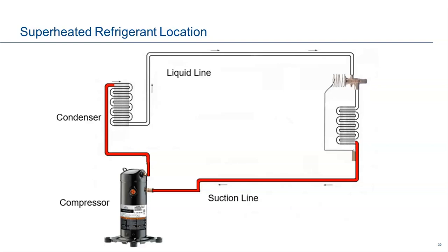If you have a 10-to-1 compression ratio, that is a low temperature refrigeration system. A 5-to-1 is usually a medium, okay? And a 3-to-1, somewhere thereabouts, is an air conditioning system, okay? It doesn't mean that it can't be 2.9-to-1. It just gives you a ballpark figure, okay?